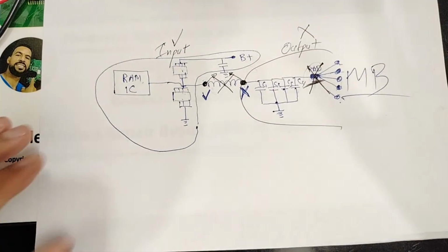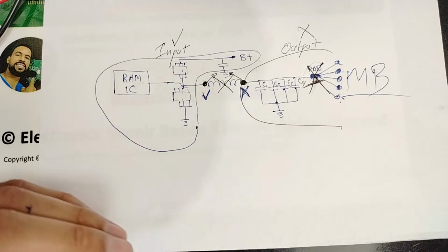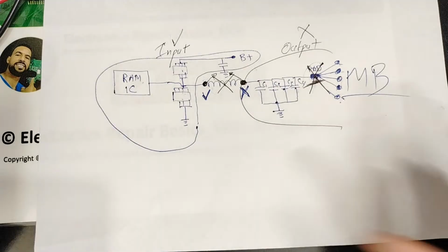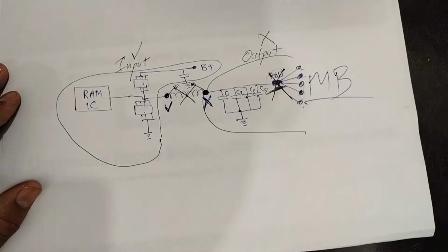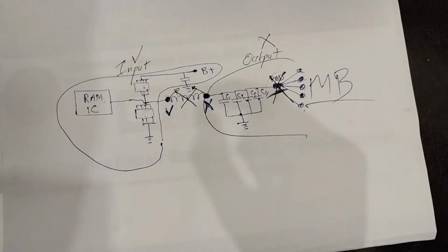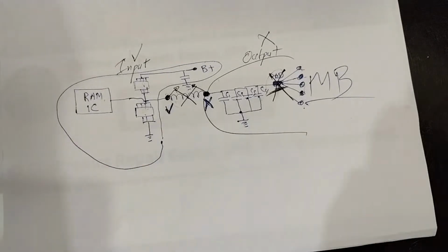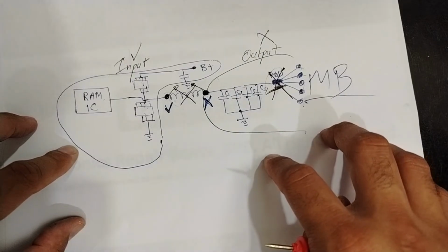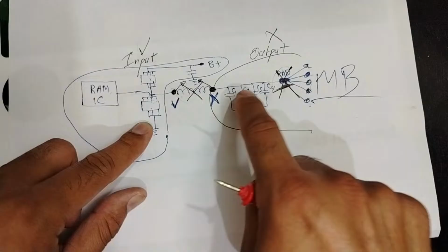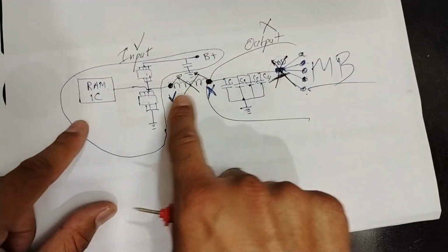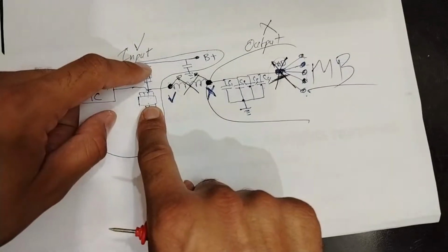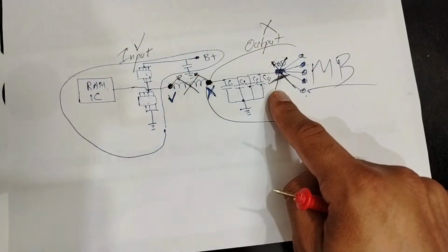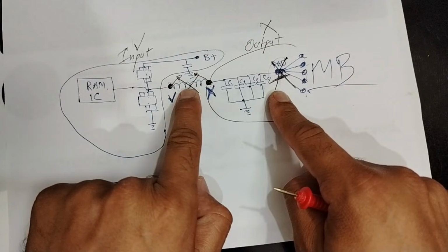My friend, please, sorry, because sometimes I disappear. But what is the most important here? I teach you how to remove the fewer components and detect the short. Because other technicians remove components randomly. Every component. You have a short here, you remove the IC. No. The MOSFET, you remove this one, you remove this one. No. For me, now, I remove just the inductor, the coil, and I separate.